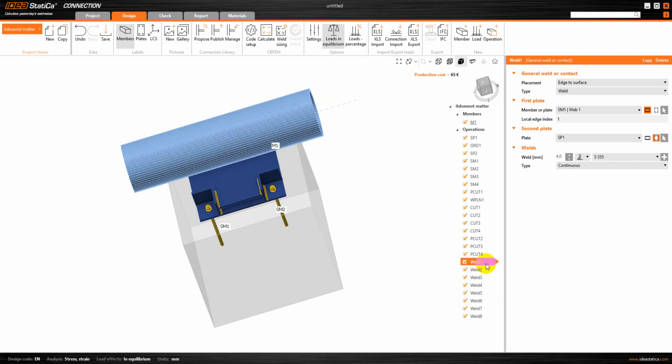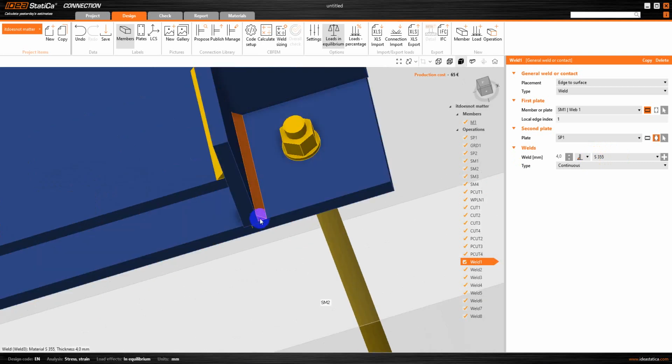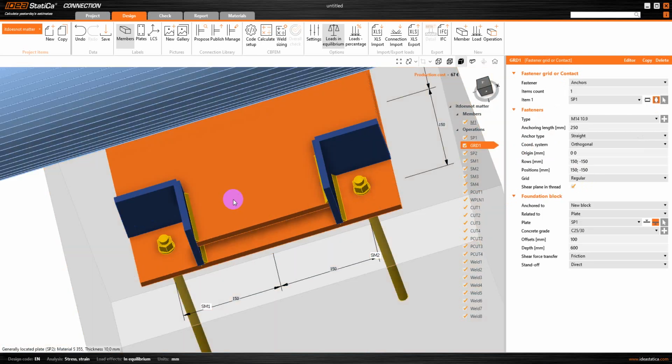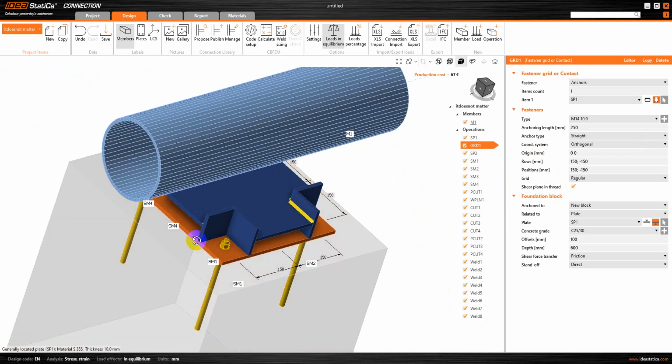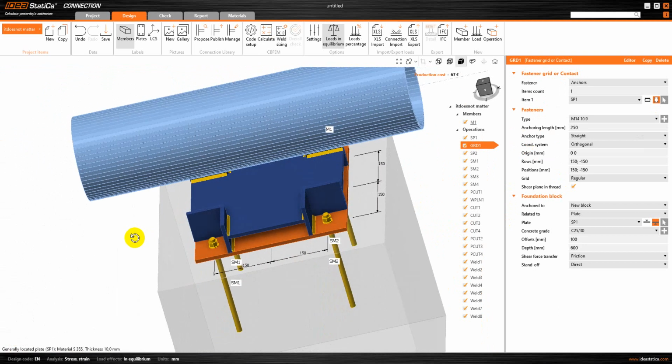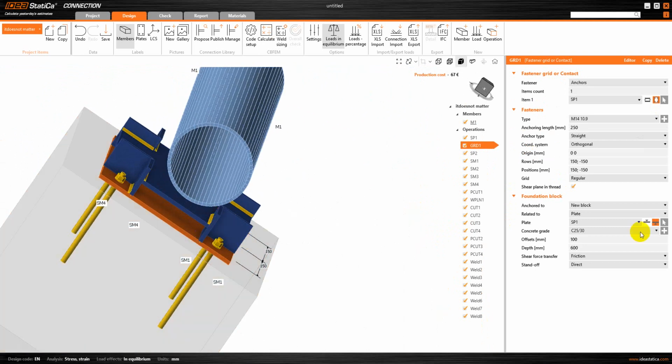And then if we want our weld, so this is like we can see the weld from this side, but if we want weld on only this portion, then what we can do is let us just go to butt weld, and then if we go to SM1, we just want to weld on this portion to this portion.